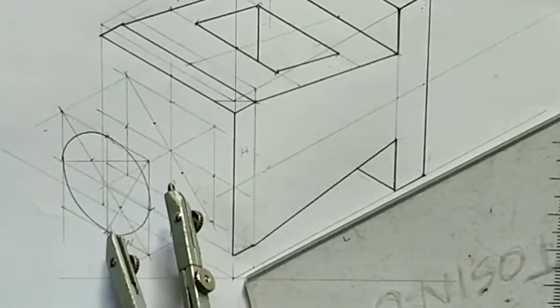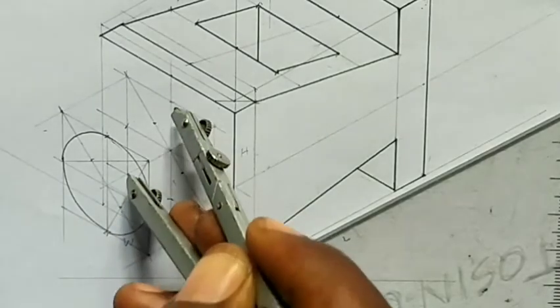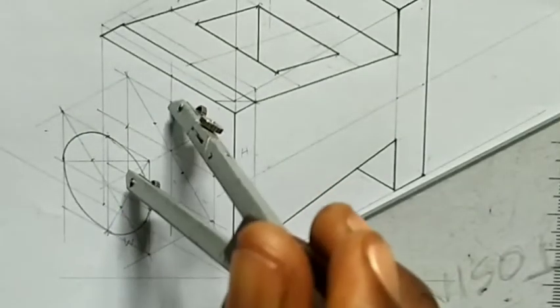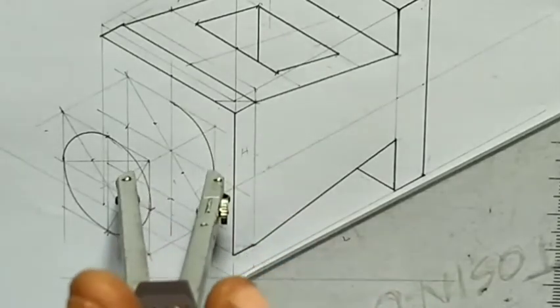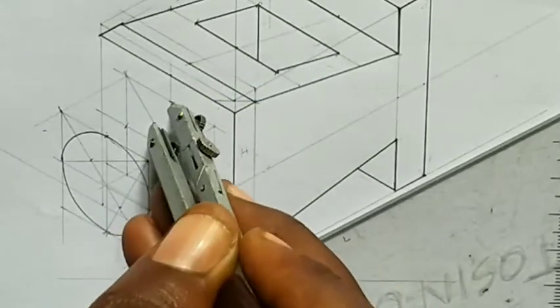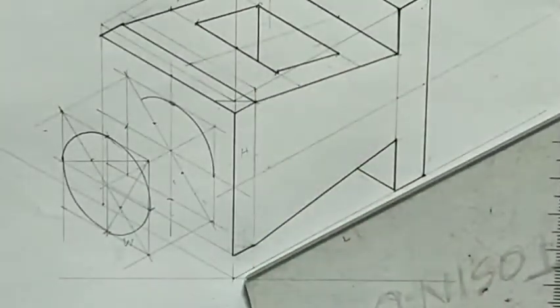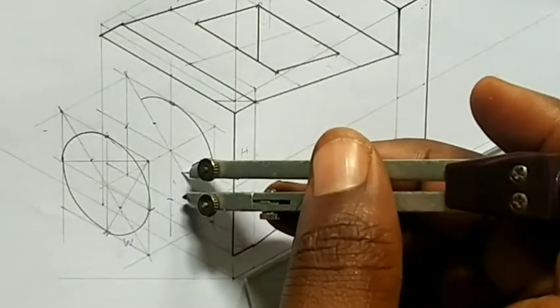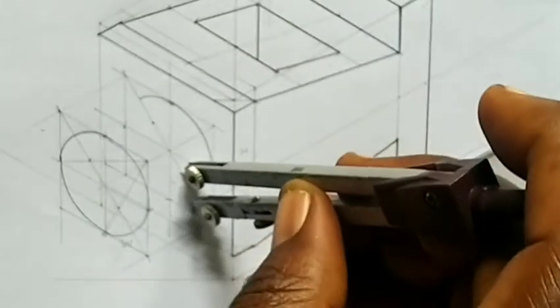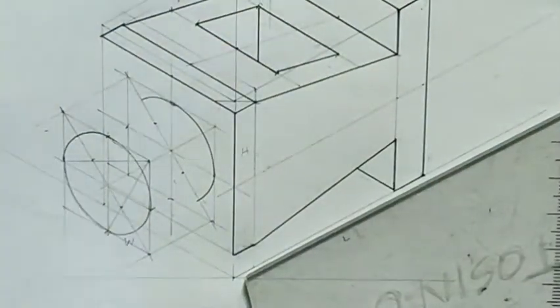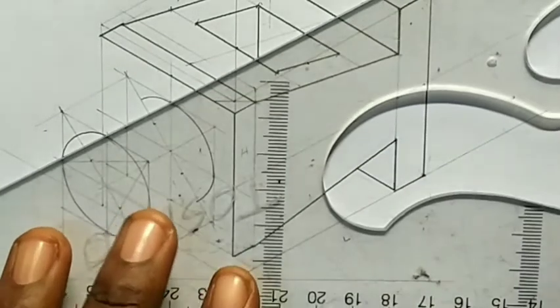So I'll now take my compass. I'll place it here at this point where they meet, which is here. I'll take it to this point and I'll draw my curve here. Right? And I'll place it at this point too. Take it to this point and I'll do the same thing. I will not move it, I'll just move it from here to touch here. Can you see that? And I'll come here too. I'll do the same thing. Get it to this point. And I'll just move this to touch here. So what I'm actually trying to do is I'm going to join this point to this point, and this point to this point.